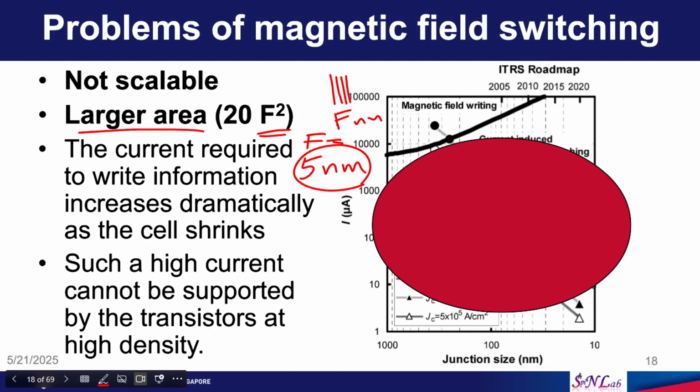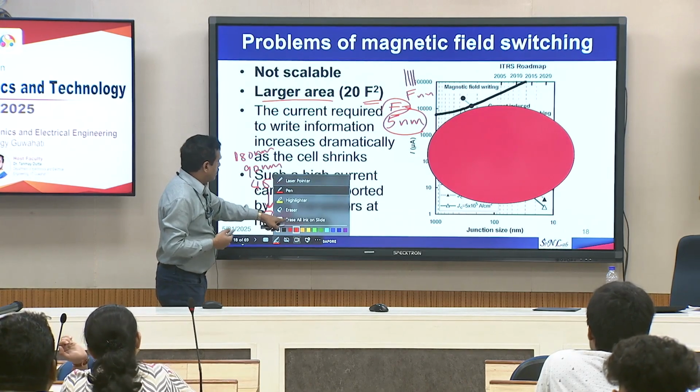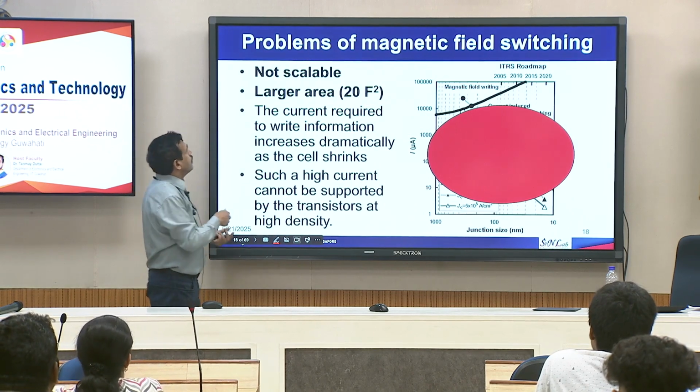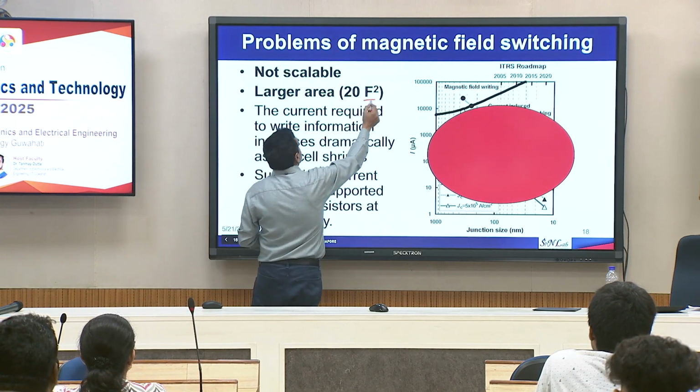If you remember historically, semiconductor technology used to have nodes like 180 nanometer, 90 nanometer, 45 nanometer and things like that. Now we are in the 7 nanometer node, 5 nanometer node. Basically these numbers represent F, which is the minimum feature size we can achieve using lithography, and we express the area occupied by a particular memory cell based on that number.